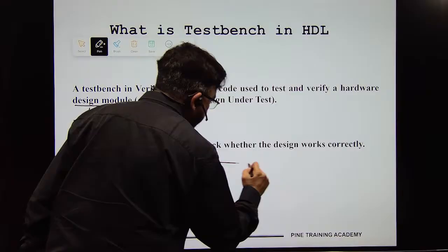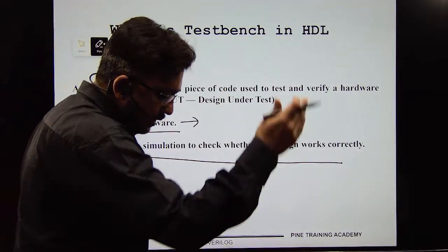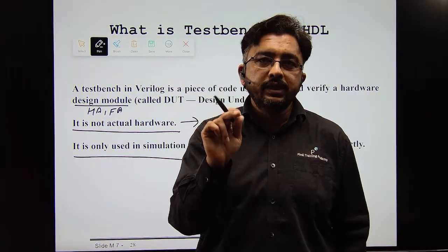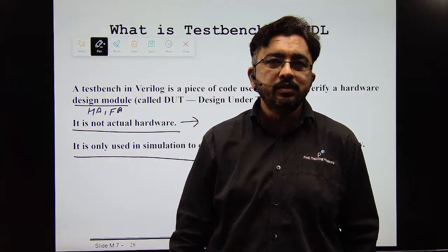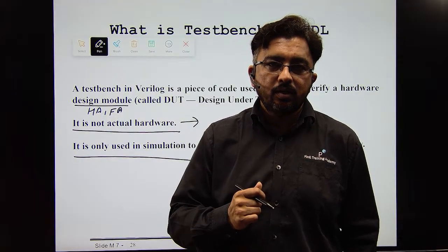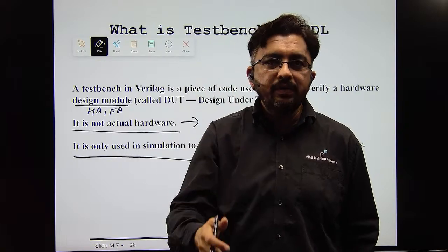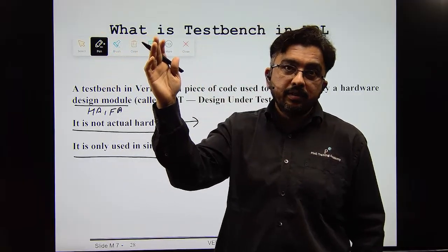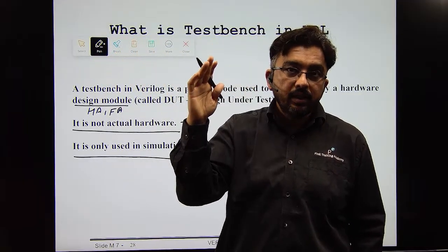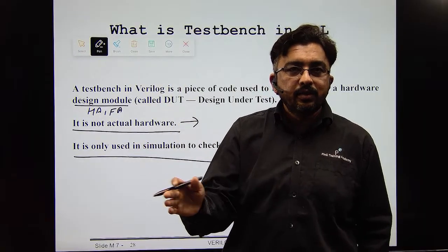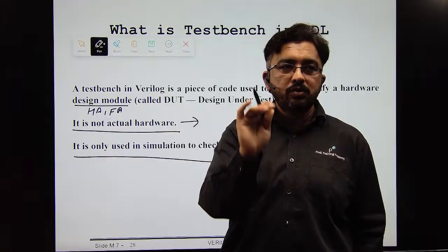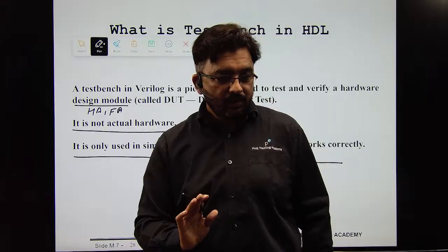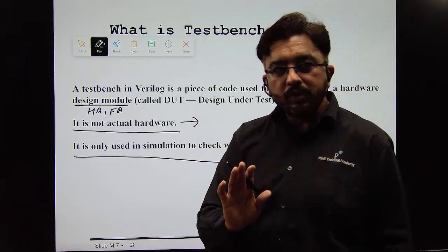See, it is clearly mentioned here. I have 100 inputs, I have 200 inputs. I cannot force them one by one, as I mentioned in simulation in the last few classes. Even if you have 25 or 20, you have to force them one by one for every possible case, saying let me try this, let me try this. You cannot force it every time: right click, force constant, right click, force constant. If you are following my classes, you know what force constant is. You cannot do it every time.